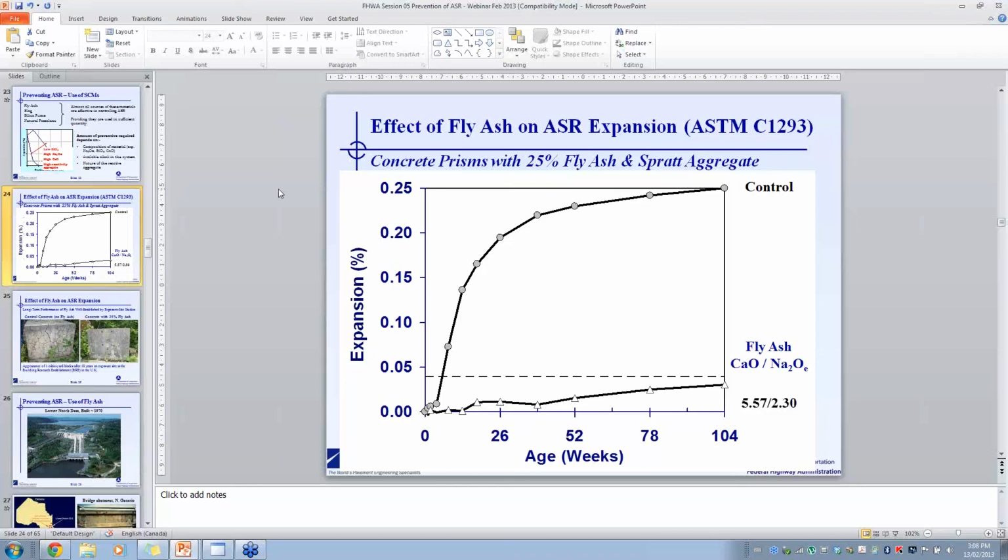Okay. The next question, is the fly ash from 50 years ago the same as today's fly ash, or have mining, processing, or pollution controls resulted in material changes? I think it's essentially, certainly the fly ashes from bituminous coals are the same as they were from decades ago. We're now exploiting different types of coal. There's more softer coals being used in power stations now. So that means there's more subbituminous and lignite coals, which means that there tends to be a greater abundance of high calcium fly ashes now than there used to be.